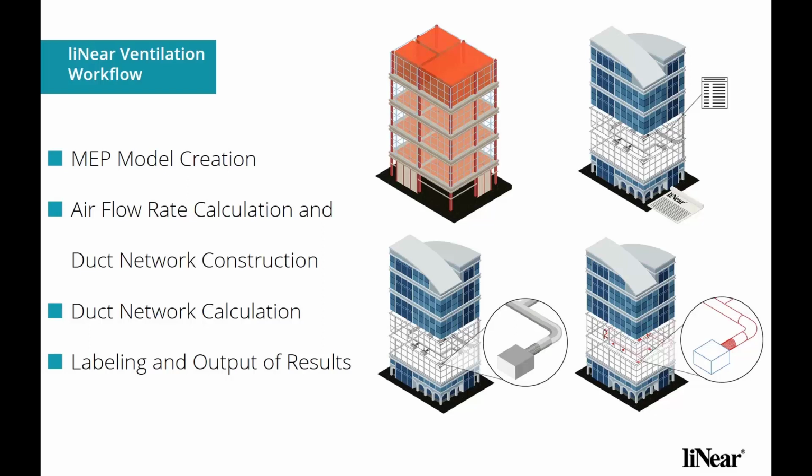The liNear duct functions and the command for automatic connection allow you to construct very easily. Supplied manufacturer libraries allow you to design with objects that are actually available. You have the choice between our liNear configurator or the device configurators of our industrial partners in order to create the central air handling units. When you construct the duct network, you can apply hydraulic calculations on it. liNear will determine the optimal dimensions of the system and calculate pressure losses. The system is also analyzed in terms of acoustic aspects.